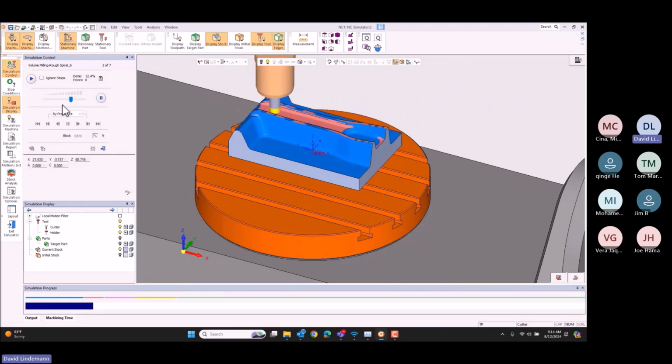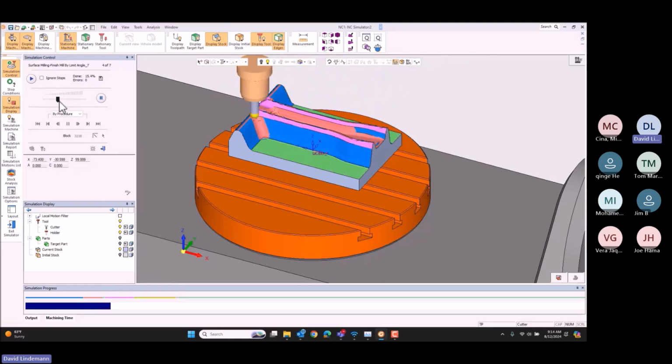Here's our next re-roughing. It's dealing with mostly the corners, the trench. There was our flat only. Now we're doing the semi, working our way down to Z. And then finally, you'd see the colors change with each tool path. At any point, you can stop, you can interrogate it. You have the ability even to check right down to the toolpath node to check for location.